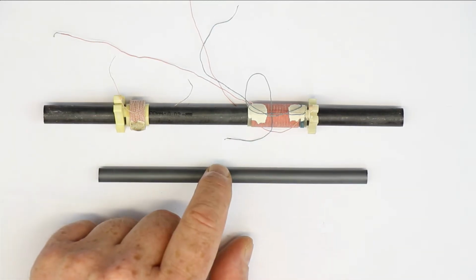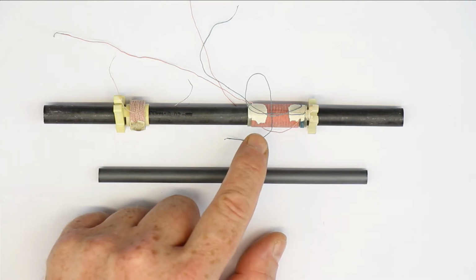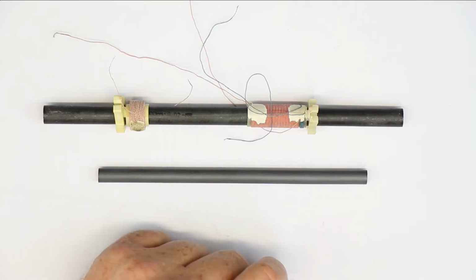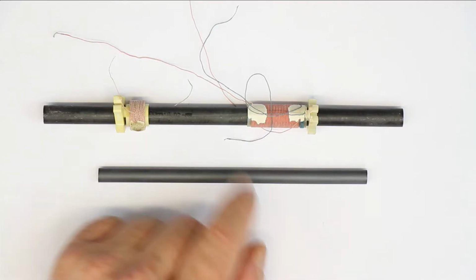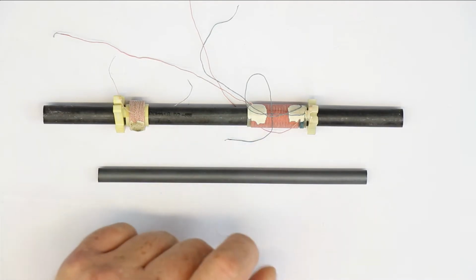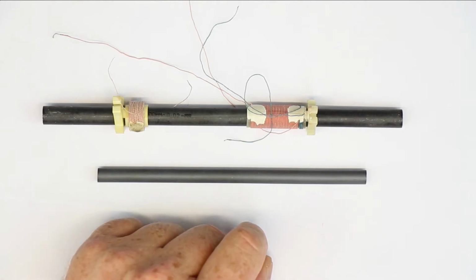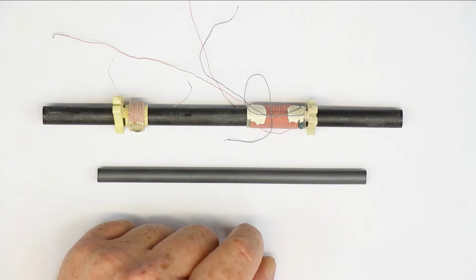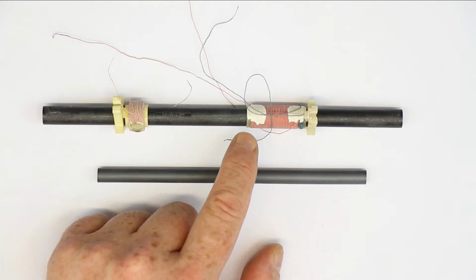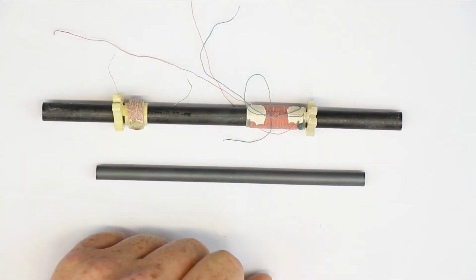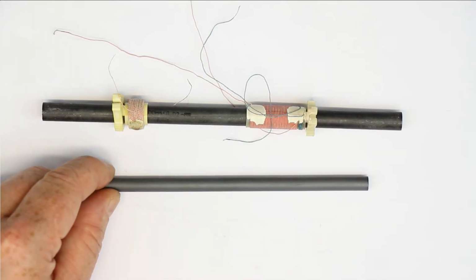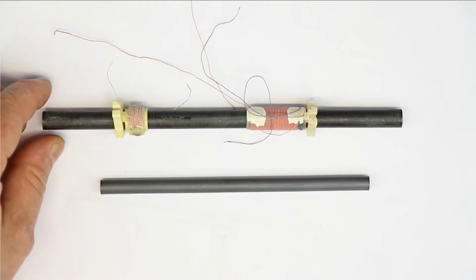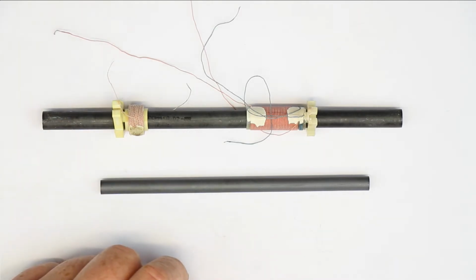Now, getting a coil of that large inductance, when you wind the coil in air, you get a very large antenna, either many windings, even up to several thousand if you have a small diameter, or you go to the concept of a frame antenna, which can have diameters in the meter range.